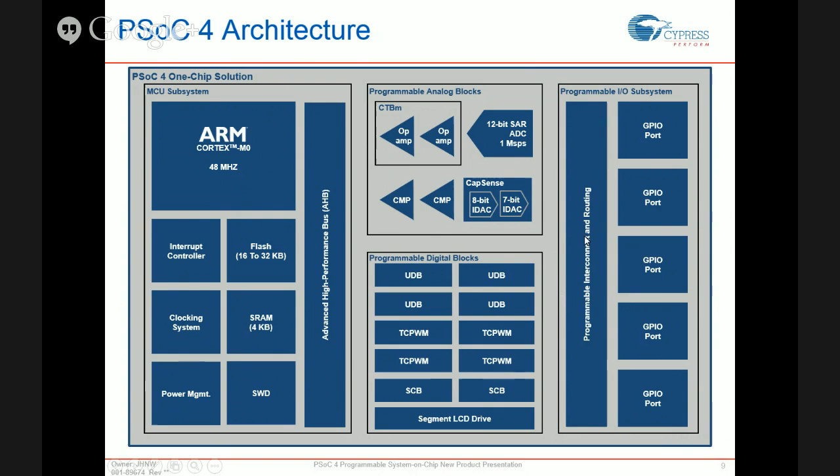And then with everything else in PSoC, your programmable interconnect and routing is also extremely flexible, and as the name suggests, is programmable. You get to decide and choose what functions are going in or out of these general purpose I/O ports, and you also have complete flexibility and control over how these various blocks inside the chip are interconnected to each other. So not only do you have these blocks available as individual blocks, you have the ability to use them in conjunction with each other, create circuits out of them, and build intelligent systems.